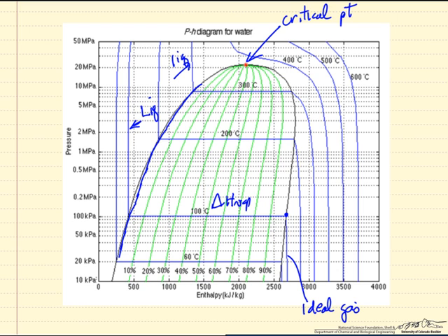So the liquid phase shows behavior that's essentially enthalpy doesn't depend on pressure significantly. We have the phase change at 300 degrees C, but notice now that as we lower the pressure at constant temperature at 300 C, so going along this line, the enthalpy decreases. Or the other way, of course, is that at constant temperature, as we raise the pressure, we actually decrease the enthalpy. So down here at the low pressures, again, it's behaving like an ideal gas. Enthalpy is independent of pressure. But at the higher pressures, and of course these are pretty high pressures, 2 megapascals is 20 bar, as we go from 2 megapascals up to about, say, 8 megapascals, there's a significant change in enthalpy.